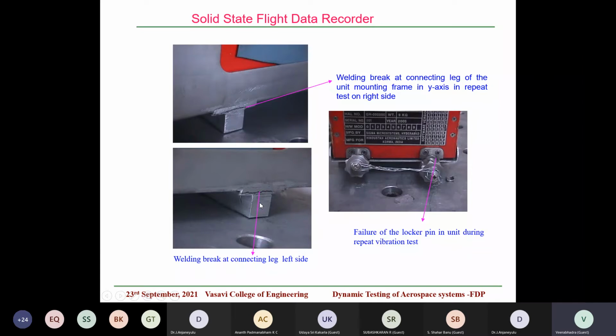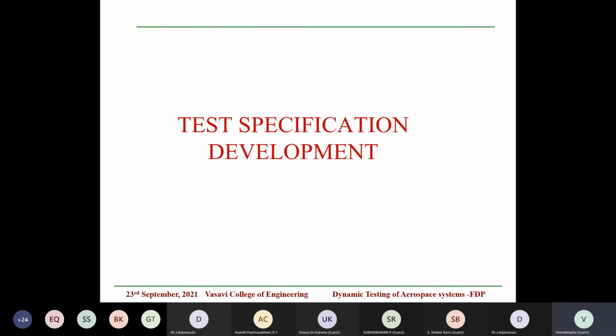The next time, care was taken that the fixture was designed properly, and the system did not have any problem. So even a badly designed fixture can affect the unit performance and even fail the system. While doing a test, it is very crucial to take care of your fixtures, test setup, test specifications, and other associated equipment, so that they are not harming your unit under test and are fit for the purpose.